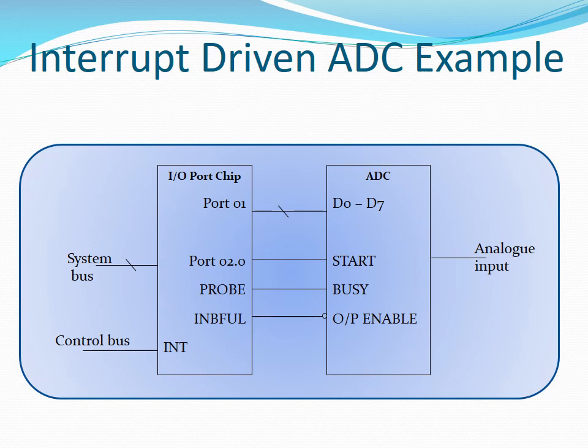The input buffer full pin on the I/O port chip is connected to the output enable pin on the ADC. This means that as long as the port is empty, the ADC is going to be enabled to place the output of a conversion on the digital output pins.